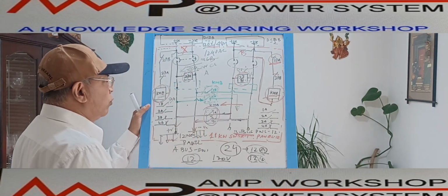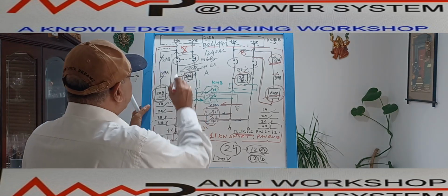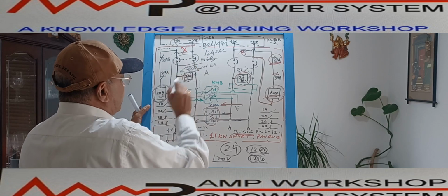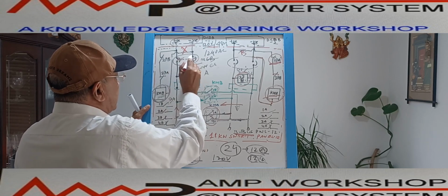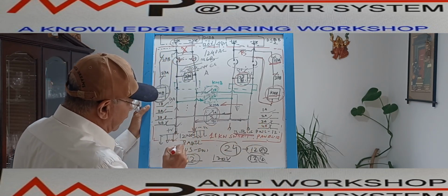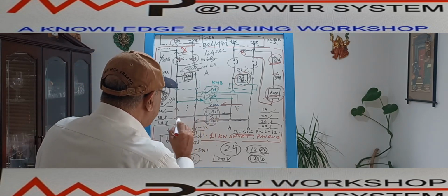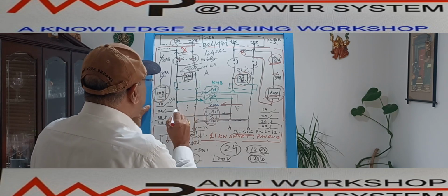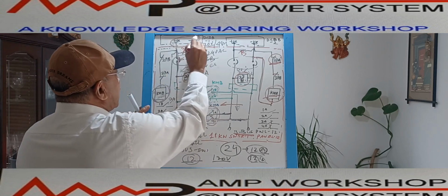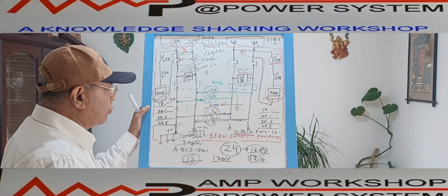But at the same time, you look into this, it is also going backward. If this power supply fails due to the main supply failing, not the MCB tripping, the MCB still remains energized and connected. In that case, when the power is coming from the B source to the A source to supply this panel, it is not only supplying the panel, at the same time it is supplying power backward also. There is a backflow, going back up to this panel. That means this panel is de-energized, but inside the panel this power is going back. That is not acceptable, so we have to cut this off.